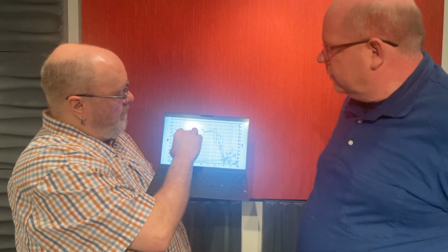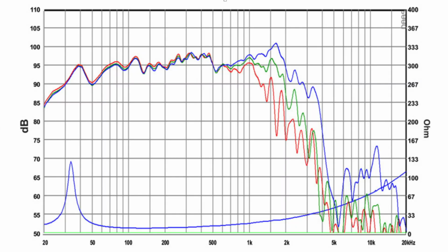What happens here for a woofer, and this is exactly why you don't use woofers above a certain frequency, or any driver above its intended frequency, is what they call beaming. Beaming is when the driver goes from being smooth at every axis like this. We're not talking about the bumps, we're talking about how close together all those lines are. That's a whole different thing. This is where the driver starts beaming, when the off-axis performance changes from the on-axis performance. We can see a pretty wide difference beginning at about 600 hertz, and it just gets wider and wider as you go.